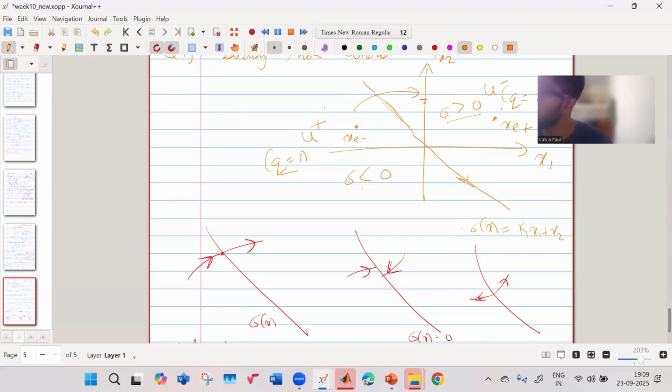So your objective is what? You want it to be on this line. You want your trajectory to go in this line. And since if it goes here, it turns off, turns on, it will keep on going like this. So this is known as chattering. This is a problem called chattering, which happens in sliding mode control. And that problem of chattering you can mitigate by considering some hysteresis band and other things. Those are there. Okay.